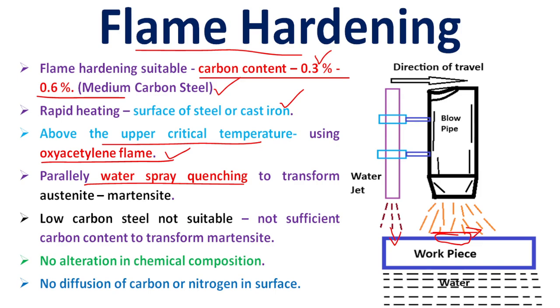This is not suitable for low carbon steel material. Low carbon steel does not have sufficient carbon to transform to martensite. So this is not suitable for low carbon steel material.